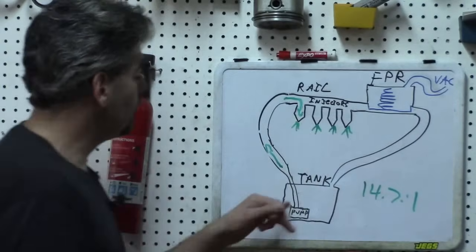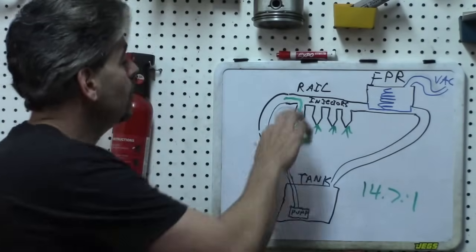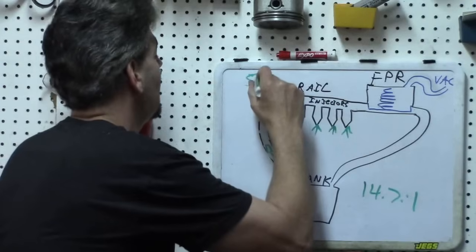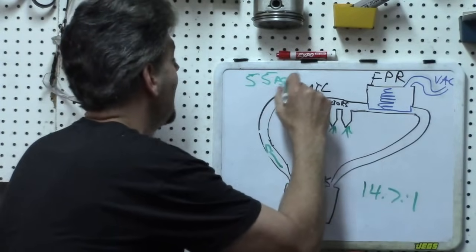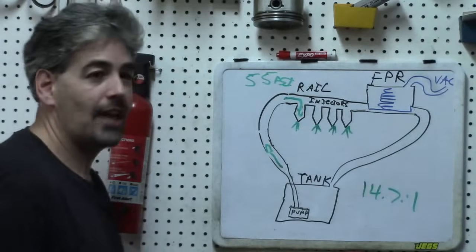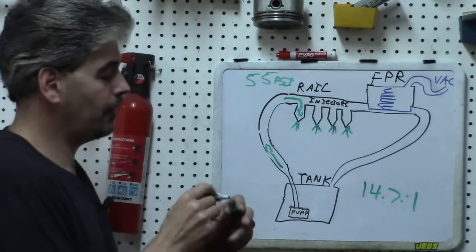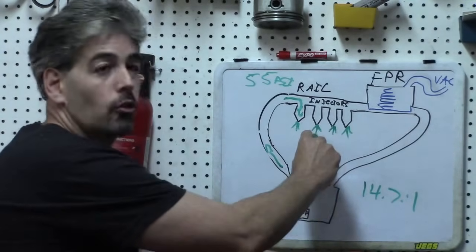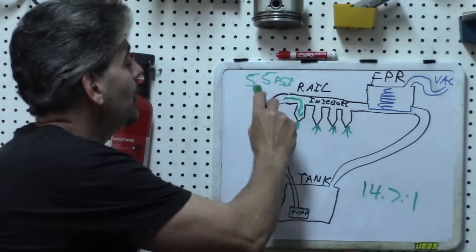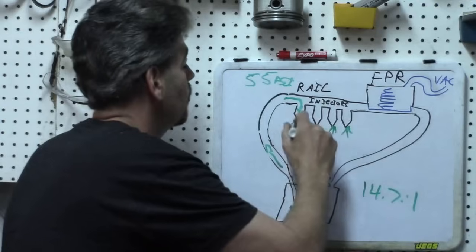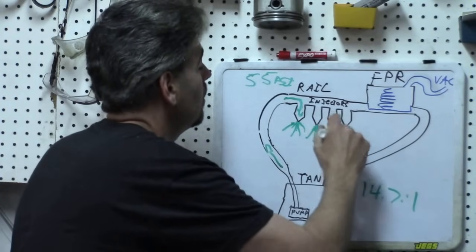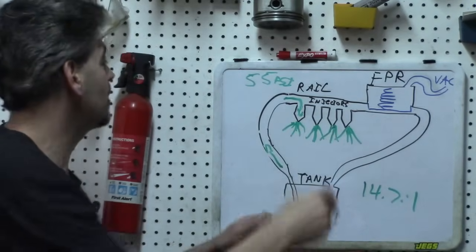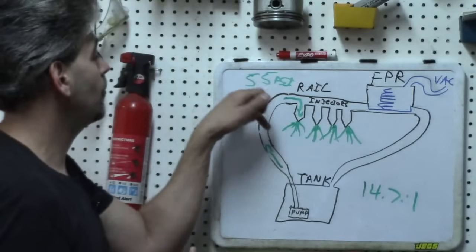If the fuel pump is delivering fuel, and of course there's going to have to be some pressure here, and let's say the pressure is a typical 55 psi, and that fuel runs out of the injectors. Hopefully you have enough of a conceptual idea of this that you would see that by opening the injectors longer, it would drop the fuel pressure in the rail because we have more fuel coming through the injectors here, which of course would be like releasing your thumb off the end of a hose and dropping this fuel pressure.